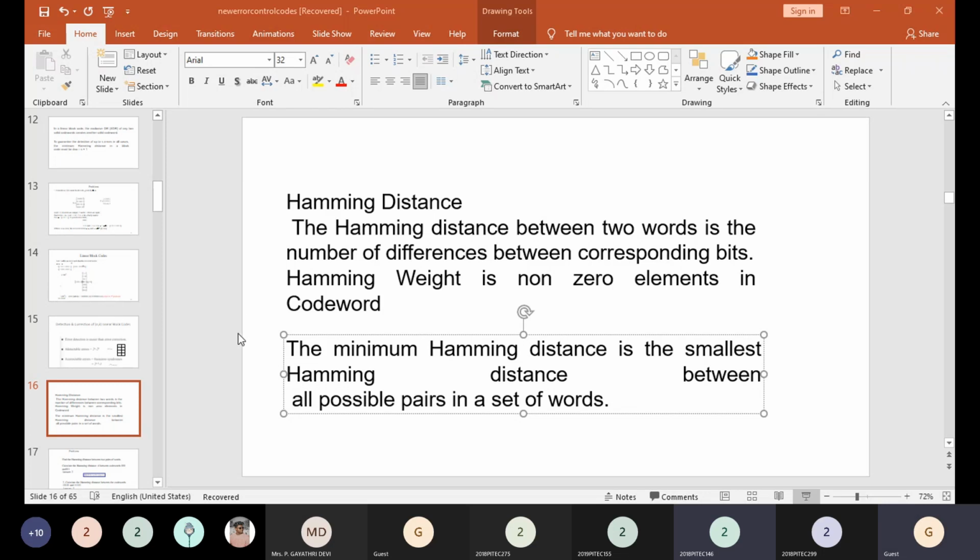So if you just add, this is 0001 and this is 0011, you'll be able to get message 3. These two messages, 0001 and 0011, are logically XORed with modulo-2 operation. 1 XOR 1 is 0, 0 XOR 1 is 1, different combinations give 1, and the same combinations, all low or all high, give 0. So 0 XOR 0 is 0.